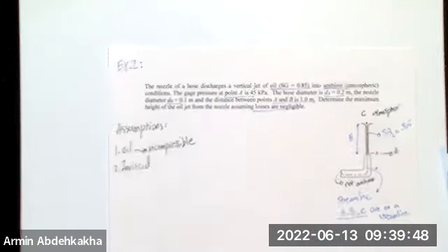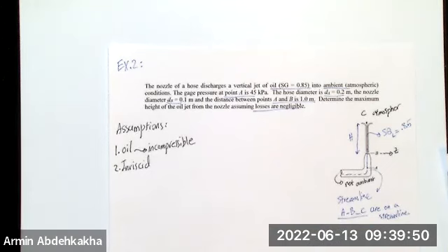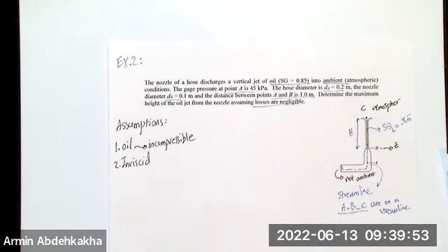What are the losses in a channel? Mostly they come from viscosity. Because of the viscosity, there is friction between the flow layers, and that's the meaning of losses. Because it mentions that the losses are negligible, you can assume the flow is also inviscid. But you need chapters 8 and 9, the pipe flow, to understand it. For now, you can say there are no losses, so there is nothing between the layers of the fluid. I can assume that this is inviscid, right?